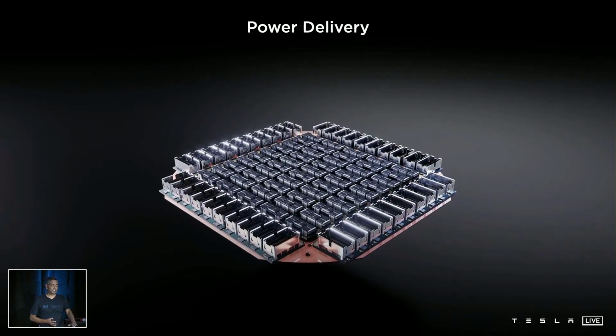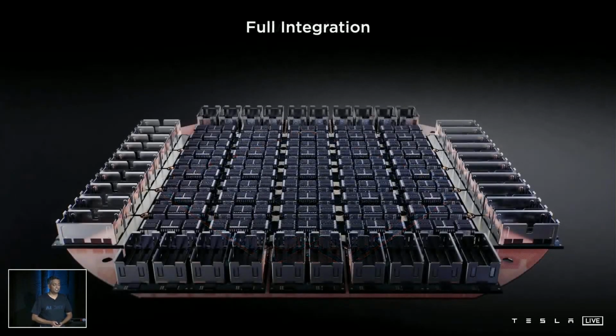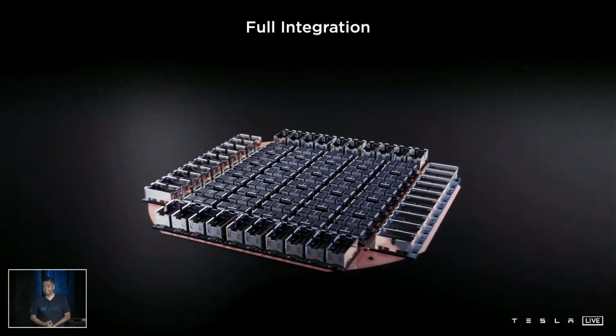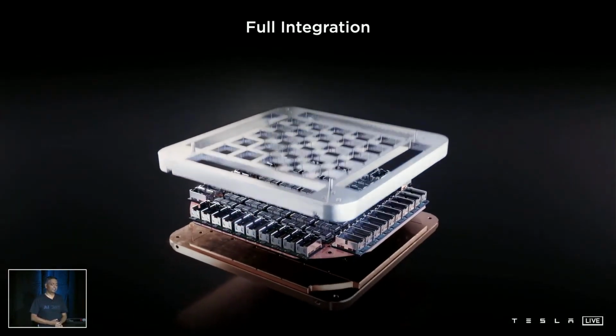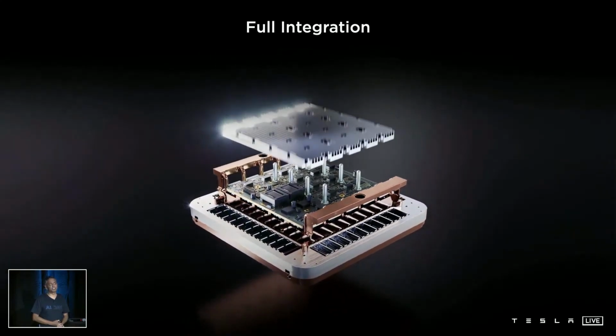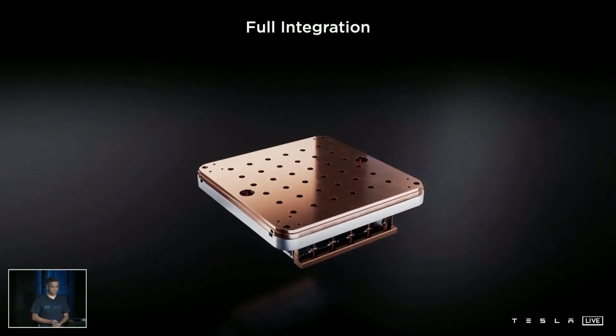So what we did here is we got chip, package, and we brought PCB-level reflow technology onto this fan-out wafer technology. This is a lot of integration already, but we didn't stop here. We integrated the entire electrical, thermal, and mechanical pieces to form our training tile, fully integrated, interfacing with a 52-volt DC input.